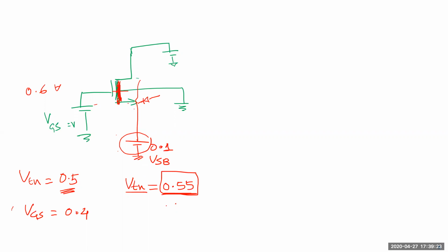Just like the way we explained, if you give 0.1 volts here, for example, I write the ID equation. I think I've already talked about the ID equation. So ID is mu n Cox W over L times (VGS minus VT) squared, let's say this was in saturation. I give 0.1 volts, so let's say this was 0.7.